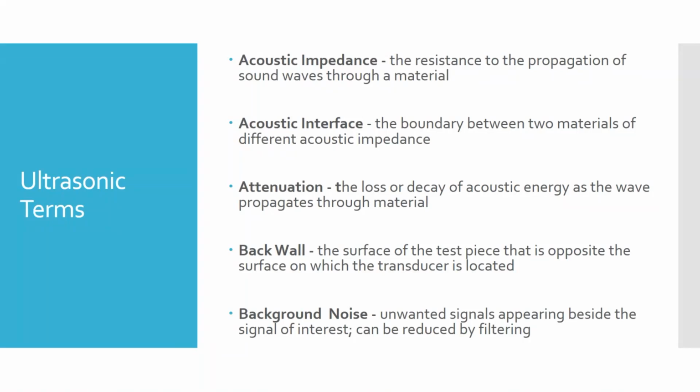So for most of what you're going to be doing, which is pulse echo testing, which one do we use then? We're going to use a longitudinal wave. It's that pulse, that wave, what they call a wave front moving back and forward. And we saw that when we sent that pulse down the slinky, it went all the way to the end and all the way back, and we could time it, right? Or when we put some kind of an obstruction halfway, it would go halfway and back and would come back sooner. That time would be shorter. And so we can use that to figure out how deep and how large the damage is in a part.